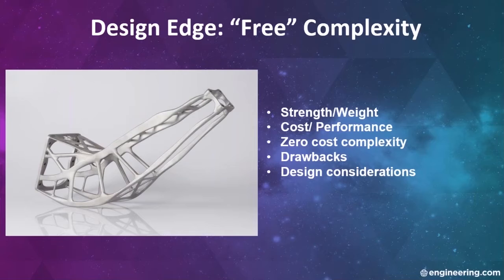Now, this image is typical of the kind of halo applications in the additive manufacturing industry that they just love to showcase. But it's important to note that a lot of improvement can be had on the path between heavy machined and fabricated assemblies and really optimized structures like this. Even designers working without the benefit of advanced simulation, generative design, or finite element analysis, well, they can render designs like this with simple, recursive, and triangulated reinforcement concepts. I mean, most of the weight and performance advantages are still there, and the additive can accommodate design changes easily after the fact. And this is worth investigating even if your design methodologies and your technologies are straightforward.